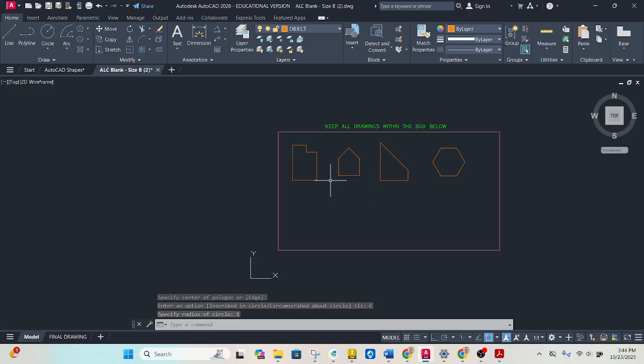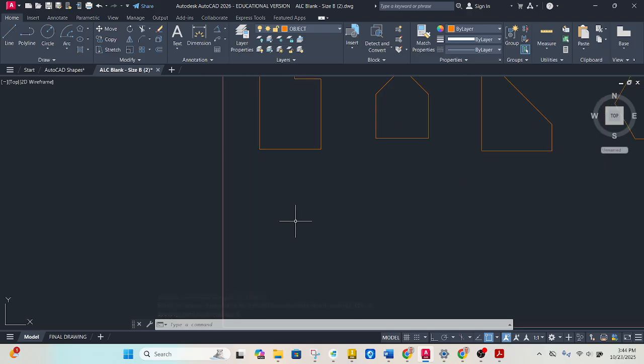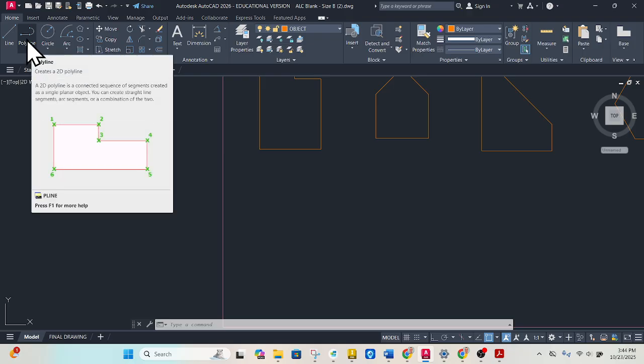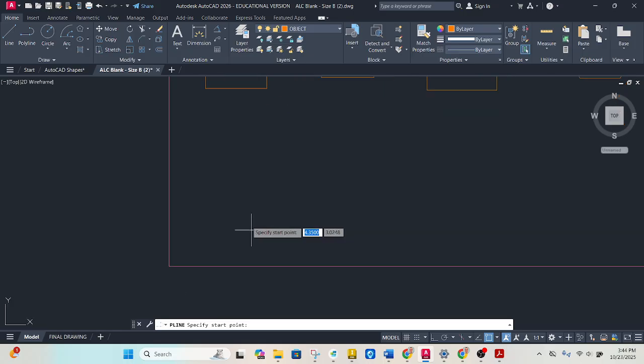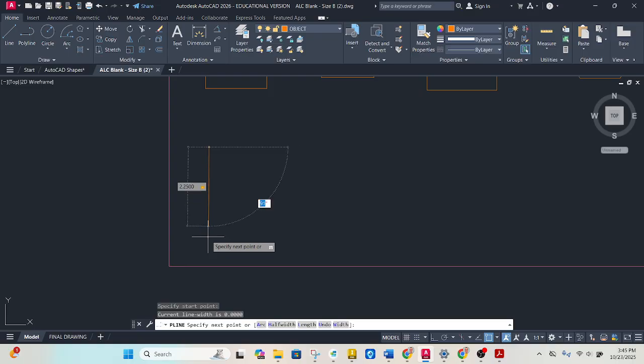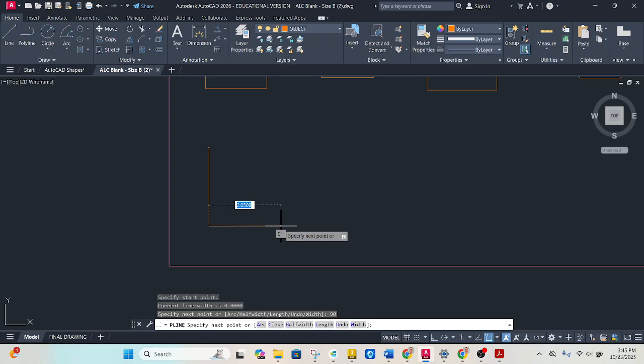Beauty. All right. And next is the kind of door shape. So I'm going to go to a new tool. This is called Polyline. So I'm going to click on Polyline, and the magic of Polyline is that it allows me to combine more than one type of line, including arcs. So let's start, let's do the top corner here, and then go straight down, and it goes 2.25, tab, 90, enter, and it goes to the right, 2, enter, and then up,